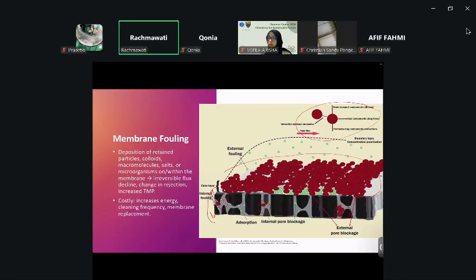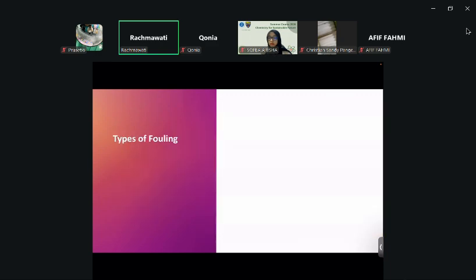And you can see that the external fouling, the red one, actually hinders the green one which should pass the membrane, but now they are hindered by the presence of this fouling. So now you can imagine that the rejection becomes smaller, the flux becomes lower, and there might be an increase of the osmotic pressure over here, which opposes the hydraulic pressure applied for this process.